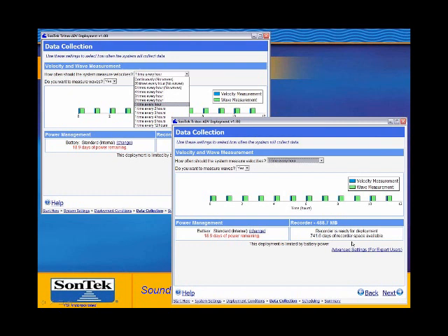Okay, next question here from Doug in South Carolina. He's asking whether the velocities average over the entire water column, and the answer to that is no, Doug. This is an ADV-based system, meaning it is a point velocity system. So it is not a profiler. We're not looking at the full water column, just at a single point.